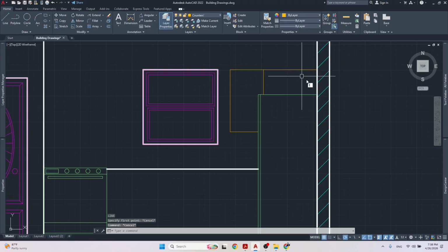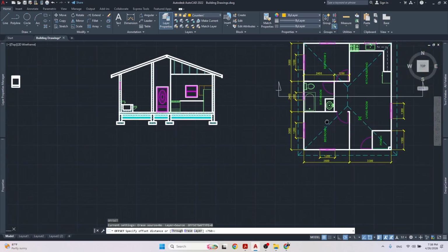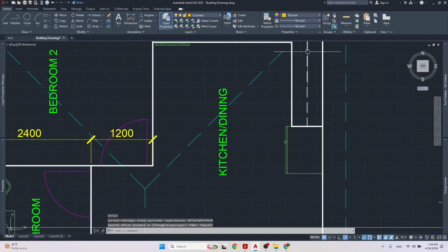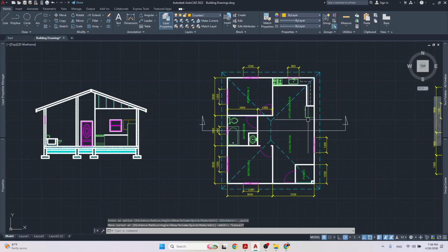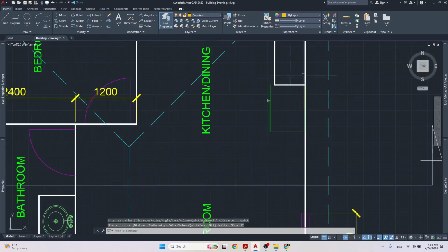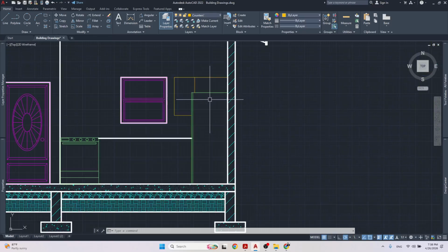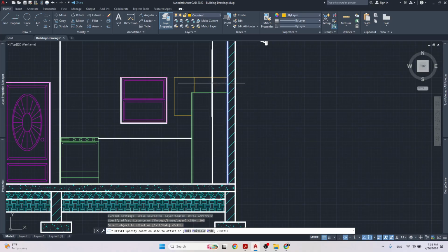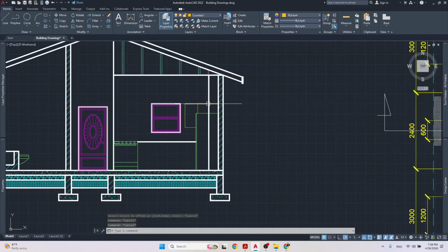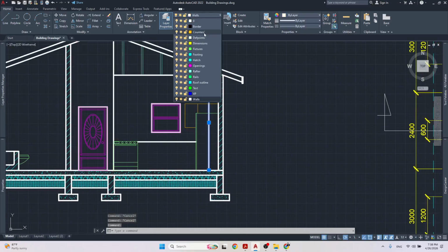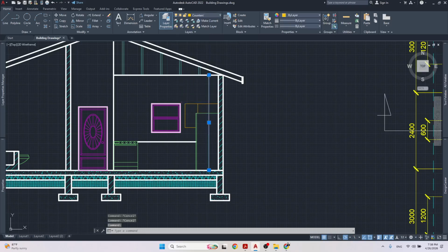1 second. I'm going to offset this line 1 foot because this cabinet coming out here is 300 millimeters, 1 foot. So I would be seeing the top part of the cabinet that comes out. The fridge will block out most of it, but let me just offset 300 millimeters coming out this way, and this is where the line would run. All right. So let me just switch this to the counters layer, and then I will trim away.